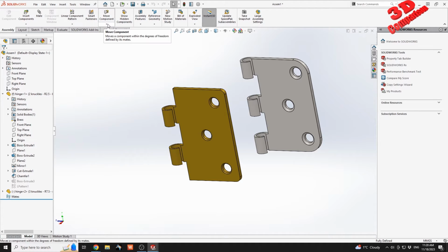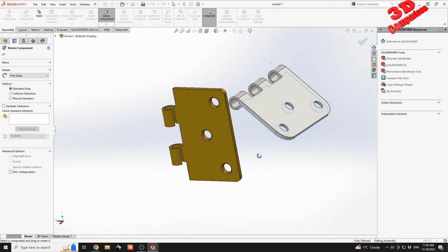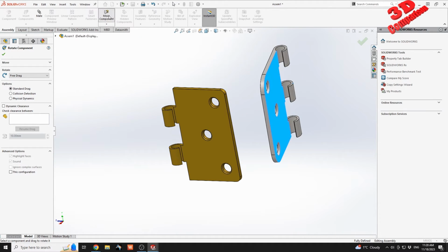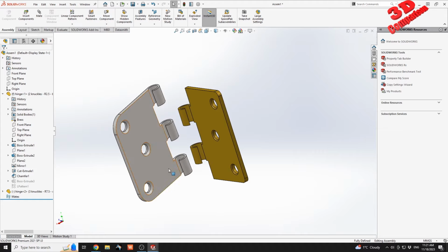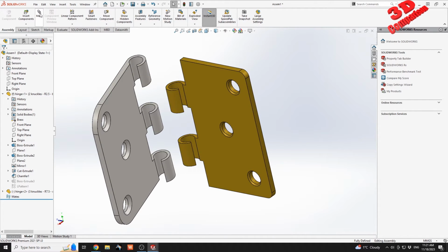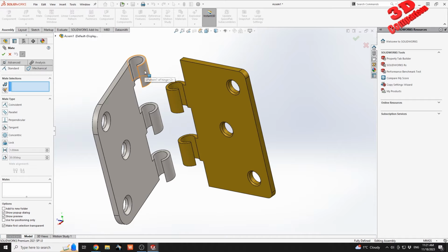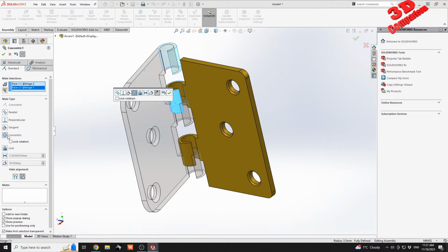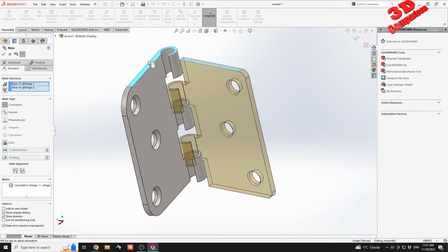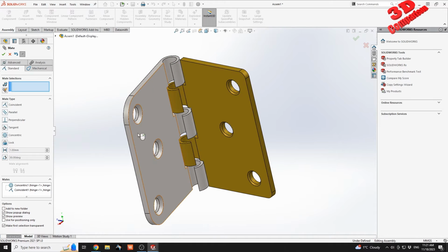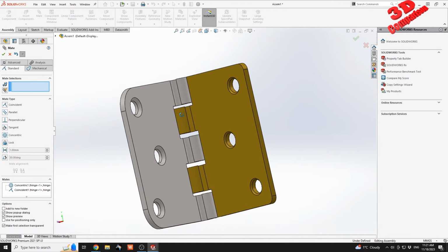I usually prefer to have the part a little bit rotated to make it easier for SolidWorks. So I know that this will be rotated like this one, and afterwards with move component I'm gonna slightly position it within, let's say, the intended assembly position. Afterwards I will go to mate and I can add a concentric mate over here. Okay, I'm gonna click OK, and I will also add the coincidence between the top part over here. So we're gonna have that position over here.